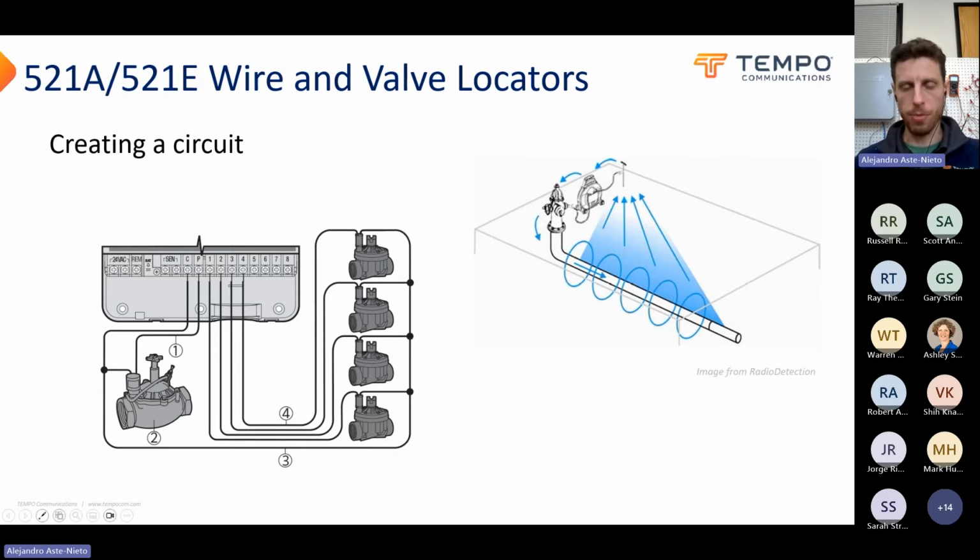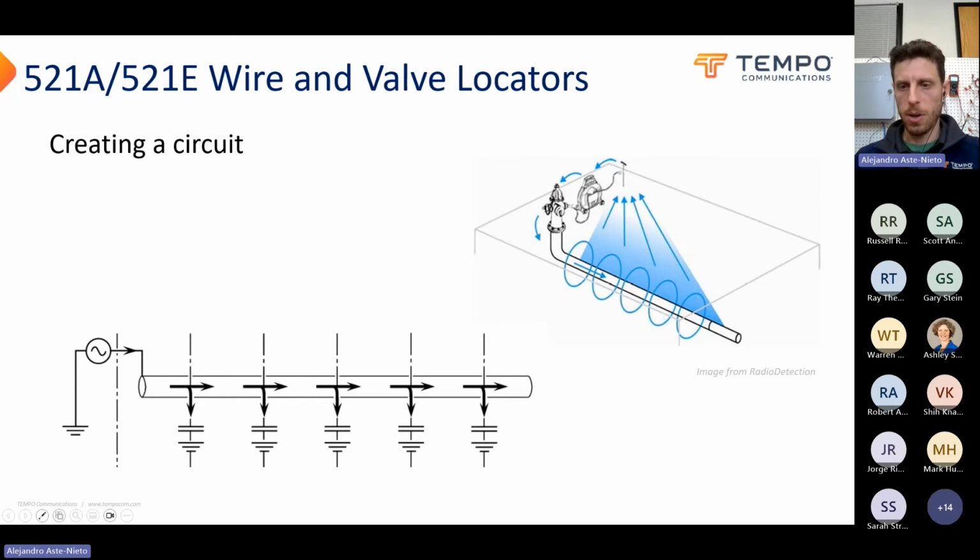That's the easiest way for the circuit to go, is through the insulation of the wire, which is acting as a little bit of a capacitor, which AC can pass through at higher and higher frequencies. So little bits of signal are being lost along the way, creating their own little circuits everywhere along the way, leaching off the signal via capacitance. And a long enough wire buried in the dirt is going to be grounded via that capacitance. So a wire laying on top of the dirt will not carry signal nearly as well unless you actually ground it at the far end.